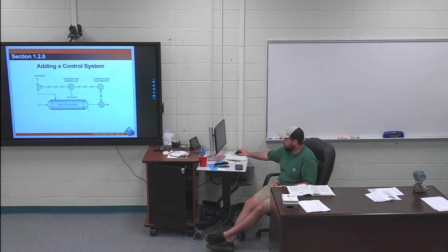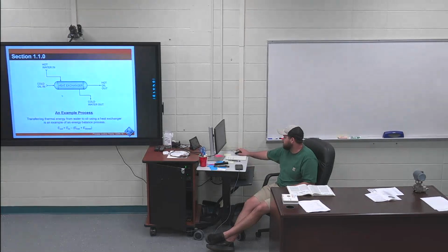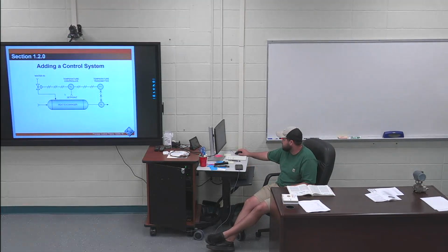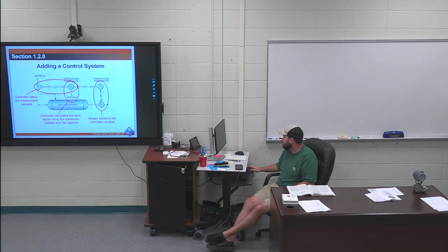So our loss is going to be like the friction going through the tubes, or some of these tubes can get crushed or stuff like that. Or if this pipe right here is uninsulated, the heat can get out of these pipes. So remember our energy equation: energy in minus energy lost plus energy stored. So even those tubes can store energy. Our energy out all the way at the end is going to be how hot this oil is. We're also going to have a loss for cold oil. Cold oil is going to be considered a loss.